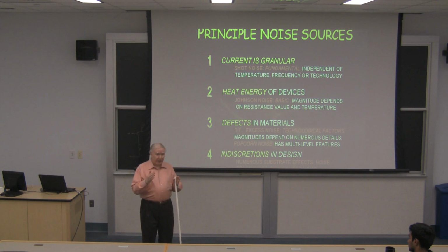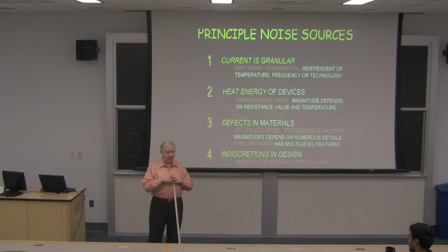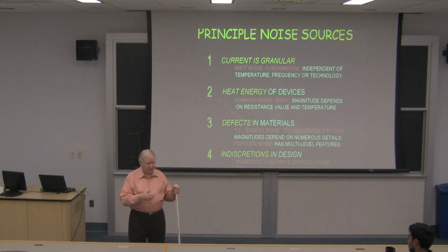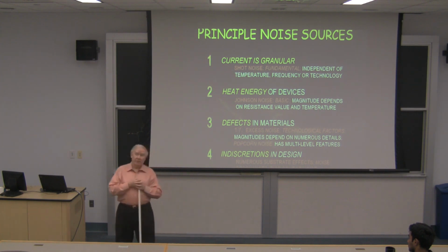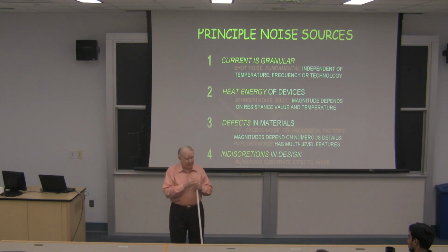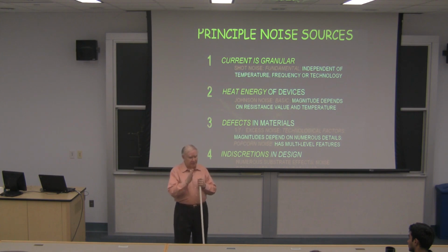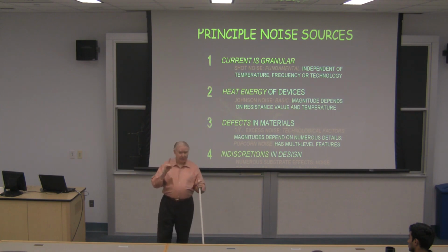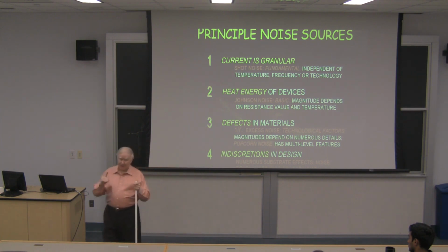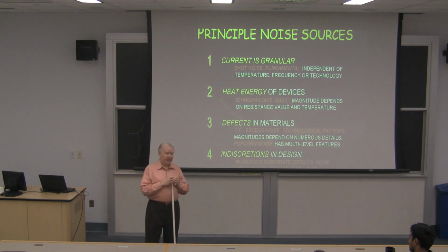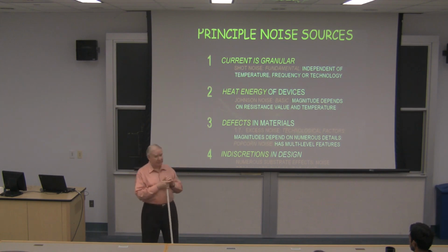And as you sweep them, I suggest you don't sweep these parameters over what you think are modest and likely ranges. Because, for example, with temperature, I talk to students about this before. I say, what temperature range do you use? Oh, minus 40 to plus 90? Well, why that? Well, that's what the customer needs. Well, that's okay, but supposing in that particular instance you swept from minus 100 to plus 300 degrees Celsius. Now, if you're smart, and I'm sure all of you are, you'll say, yeah, the models are not going to hold up. Well, that's not quite true. Most of the models do hold up pretty well as far as noise generation goes. Certainly something as primitive as a resistor is going to behave just like that.